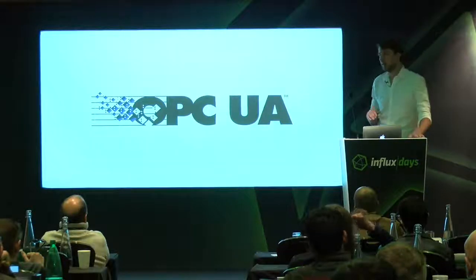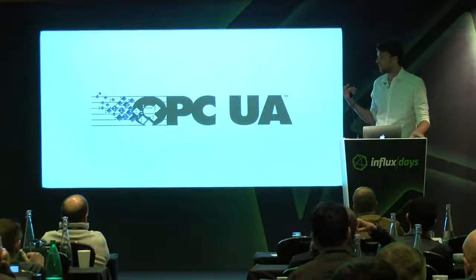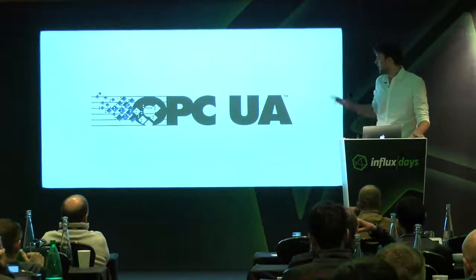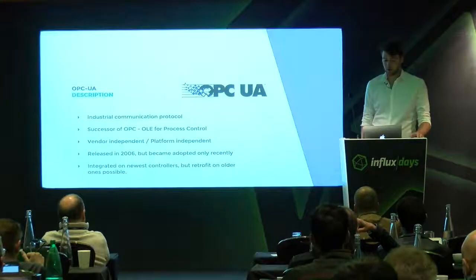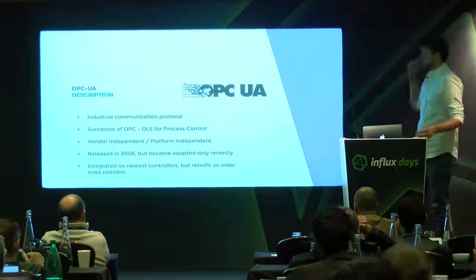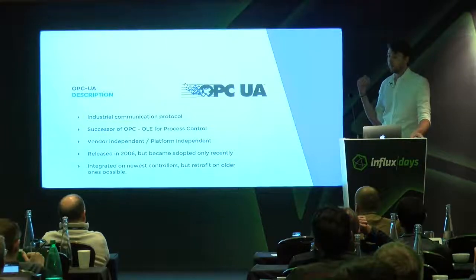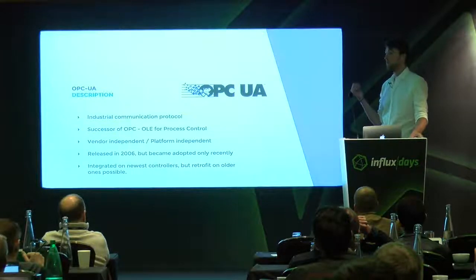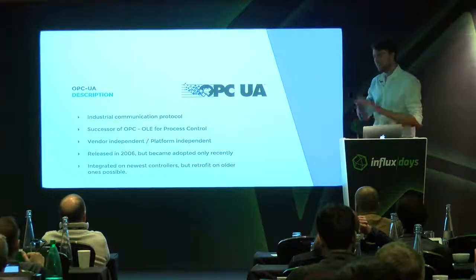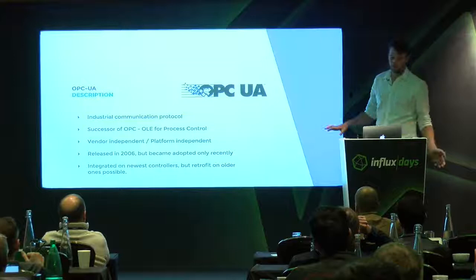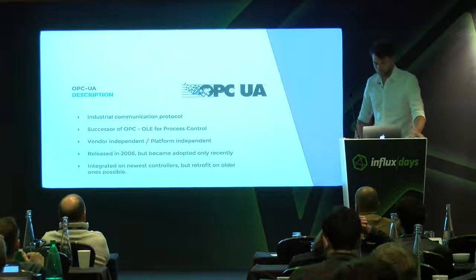I told you earlier, there were no standards in industry. There is actually one, but it's quite a recent one. It became adopted over the last 10 years: OPC-UA. It's a vendor-independent communication protocol for industry. It's the successor of OPC, which stands for OLE for process control, a very old version relying on Microsoft's DCOM, which was very messy to work with. But this one is TCP-based, open, vendor-independent, platform-independent, so it is fit for purpose for what we wanted to do.